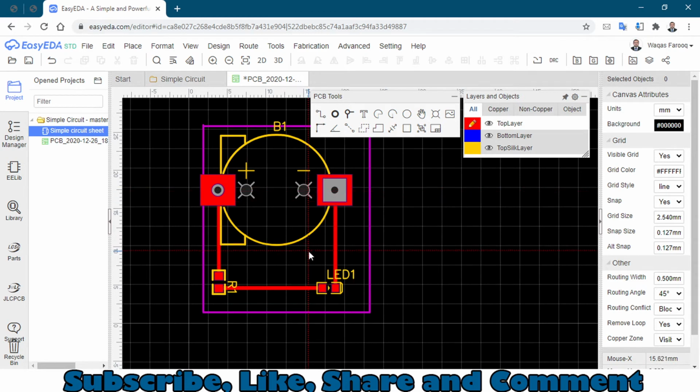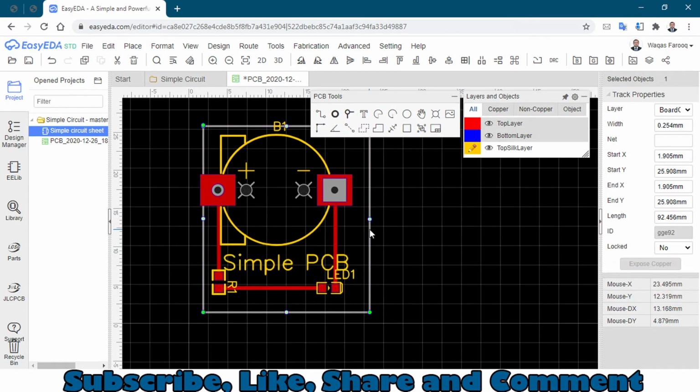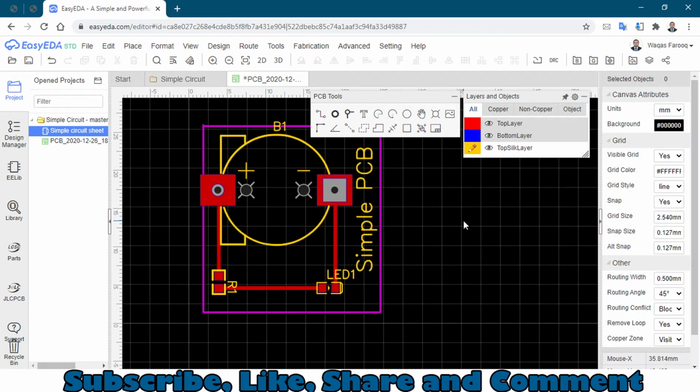After this, if we want to add some text here, like labeling these components or something else, just click on this top silk layer and click on this text, place the text here, and change the text by clicking simple PCB and click on the set part place. So it's taking a lot of place, so we can move this text by changing the size. Click on this text, click on R to rotate, and move this text towards the edge right here. Now everything looks cool.